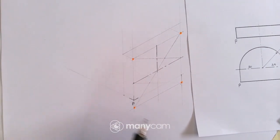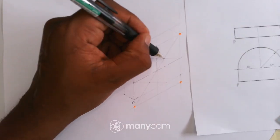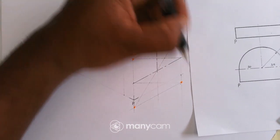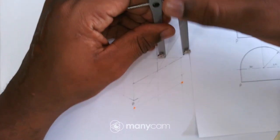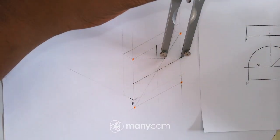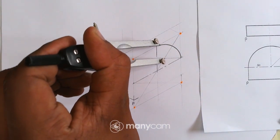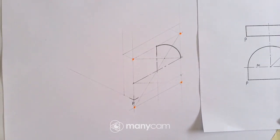But obviously now I'm drawing this arc, so I'll only focus on this point for the part there. I'll put my compass at that point, open it to that point, and then draw an arc from that point to the point at the top there, to the center line, the vertical center line.